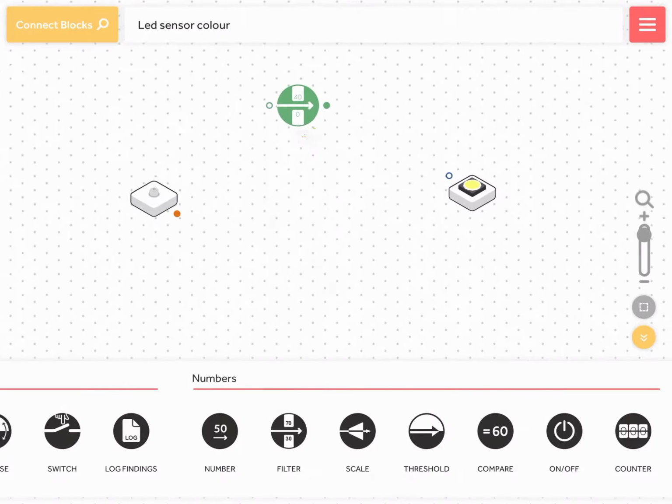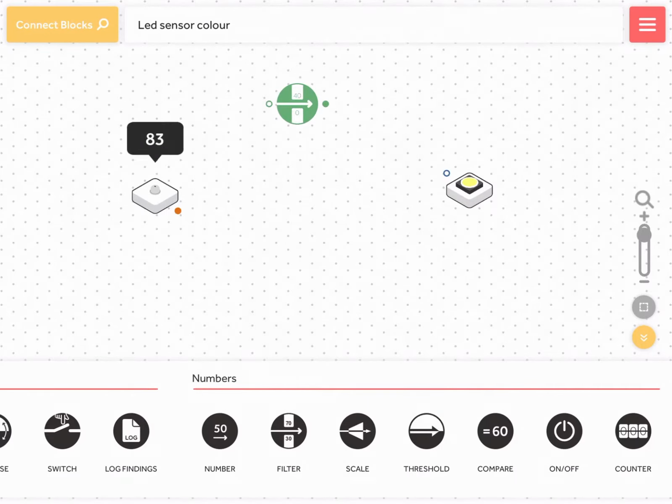Now nothing's going to happen yet because nothing's connected. So let's connect this up and see what happens. I'm drawing a line with my finger between the two dots. So at the moment, I have a filter that says pass it on when it's between 0 and 40. My hand is not covering it. When my hand covers the light sensor and the light goes down, the RGB LED turns on. Okay, but it's not changing colour yet.